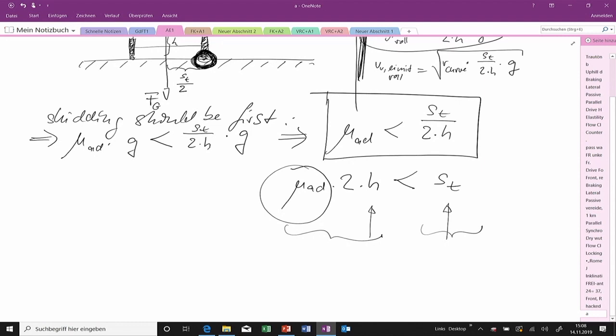And of course, also the same thing with the oscillation around the yaw axis. Also here we have an inertia, we have an elasticity, we have a aligning torque created by the tires. Yeah, you know, if you go into a curve and you take your hands off the steering wheel, it will go back alone by itself. Yeah, it goes back into the central position. That's a back driving torque created by the tire-road contact. This takes place in the vehicle, and creates a force which is similar to that spring force.